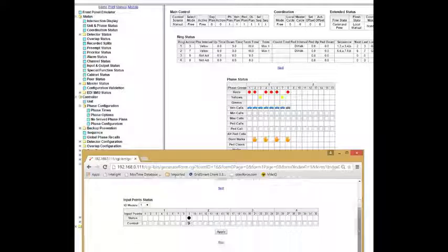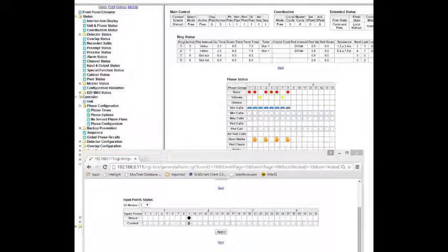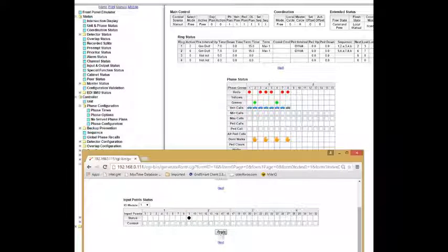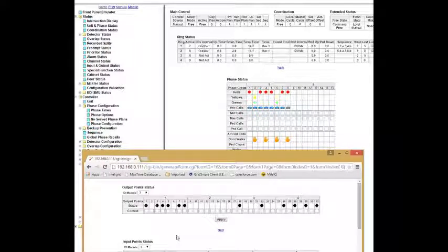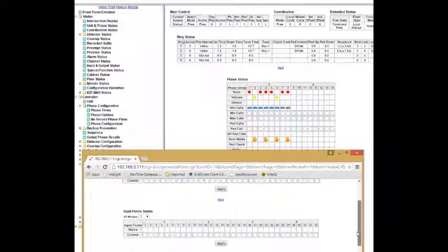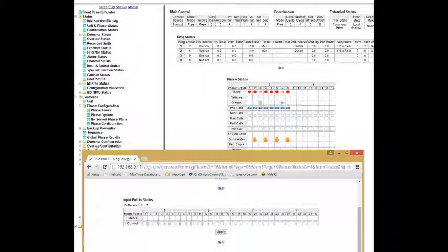You see that the apply is put in. Our input is true. We're shutting down 3 and 7. We're going to 2 and 6, and we hold there as long as the input's true. So if we had an application where we could see video or something in a big long platoon, we could actually shut down a set of phases, turn another set of phases on, and clear a queue manually.